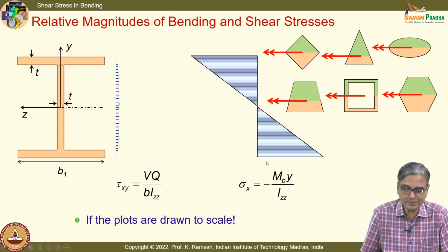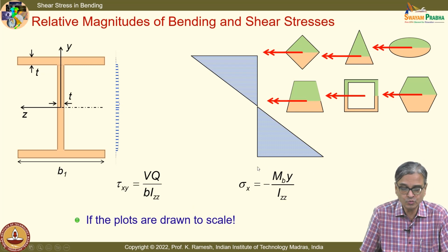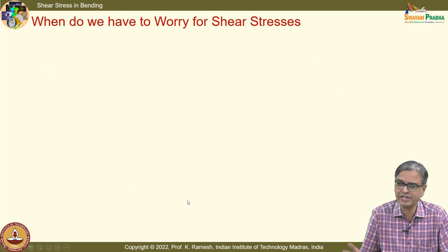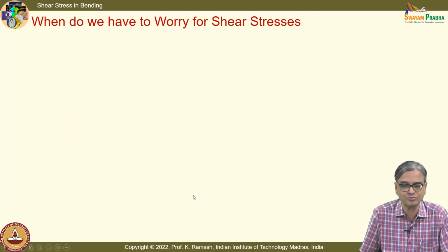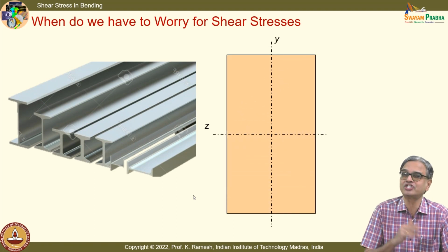So, what you will have to appreciate is, as long as the beam is slender, from a design point of view, you will know how to calculate the axial stress developed due to bending and the shear stress developed due to transmitting of shear force or variation of bending moment, whichever way you want to do that. So, I said where we have to worry, we have to consider shear stress.